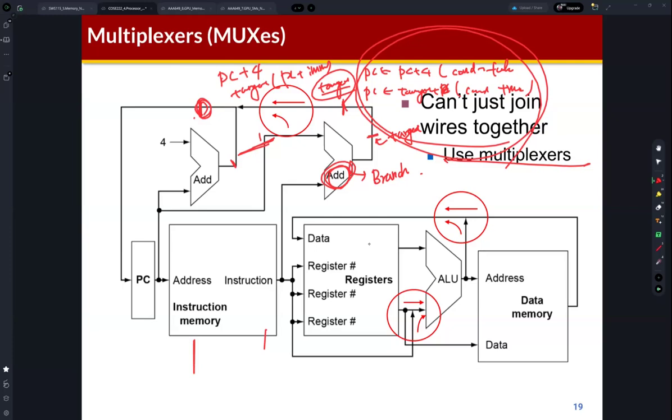So this operation is a multiplexer, right? So actually, we need to implement this part like a multiplexer, and then this one is connected to one input of the multiplexer like I0, and this one is connected to I1, and then using the selection signal, we need to select the output of this multiplexer. Okay, you have to understand.